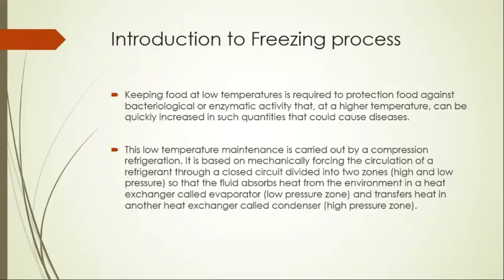There are other methods as well, like vacuum absorption chiller, also available in the market to lower your product temperature, but in the industry we widely use the vapor compression cycle because of its dominancy, because you can secure your product up to -10 or even sometimes lower than -10 degrees centigrade, but for vacuum absorption chiller you can't secure your product below that mark.